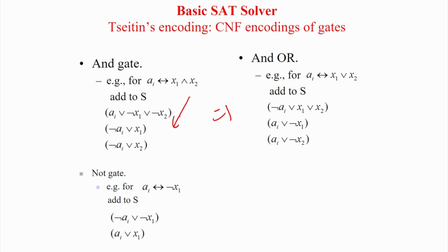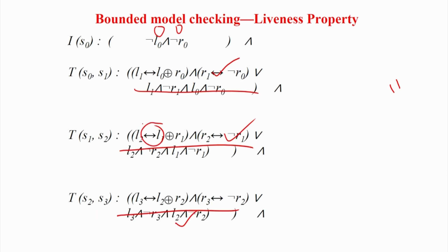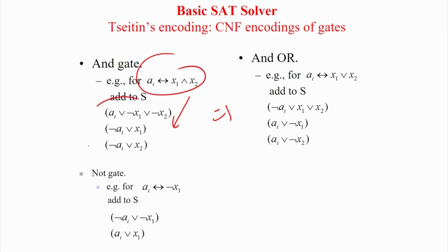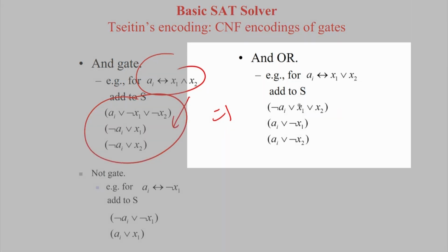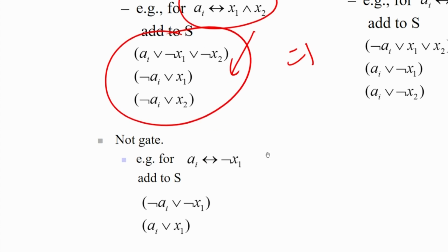Then basically this is CNF. So all the terms we have written in this case, in terms of this relationship, in carry is an XOR, but for all gates we can have a similar formulation so that the whole thing can be transferred into a CNF formula, and then SAT can solve it for you. Again, I am not going to discuss in detail. This is for the OR gate, and this is for your AND gate. Similarly you can easily find out.